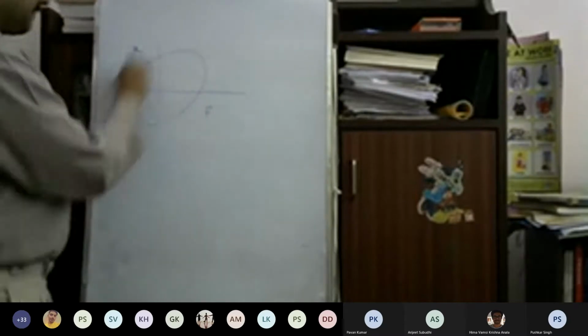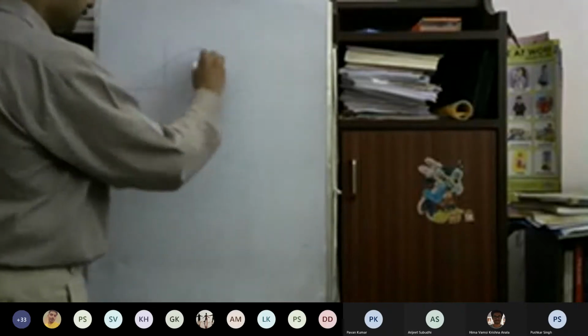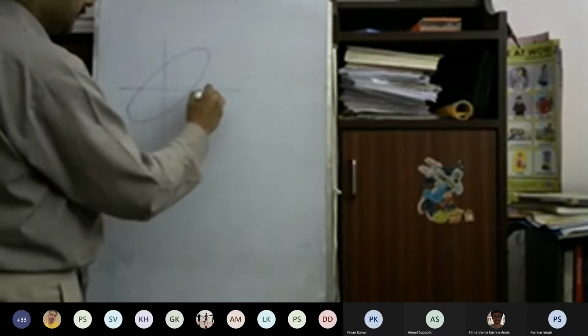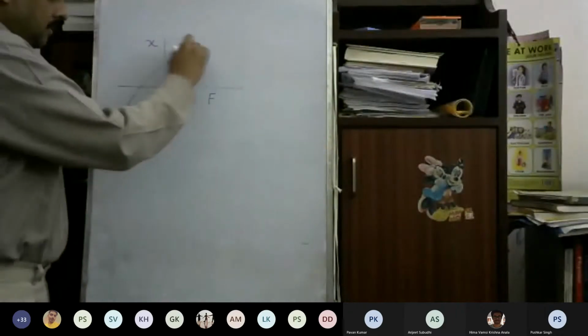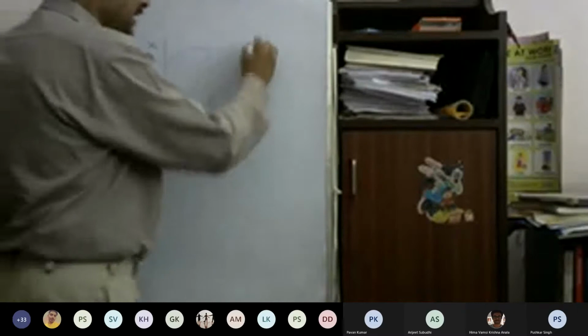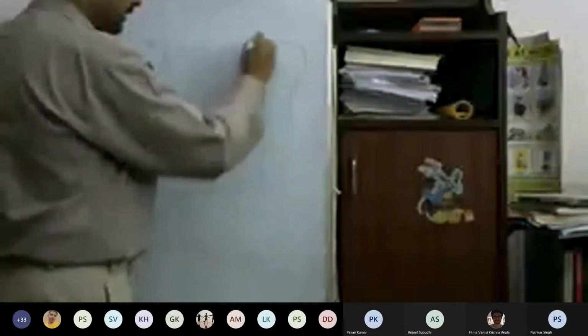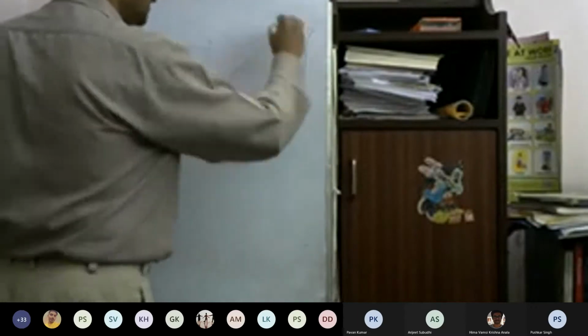Now, the hysteresis loop, which I was talking of all the time, is the curve of F and x. If you have a damper which is actually a linear damper, you will get an ellipse. But when you do an experiment, you may not get a very good ellipse like that. You may get a shape like that, or most of the time you get a shape something like that. That means the damping present is not viscous damping.